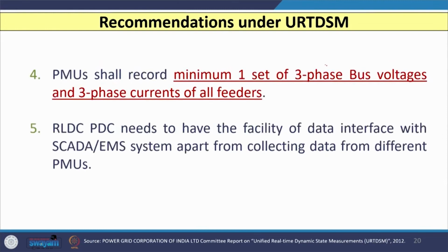The fourth recommendation is that the PMU shall record a minimum of one set of 3 phase bus voltages that are there in substations, and the 3 phase currents of all the feeders.